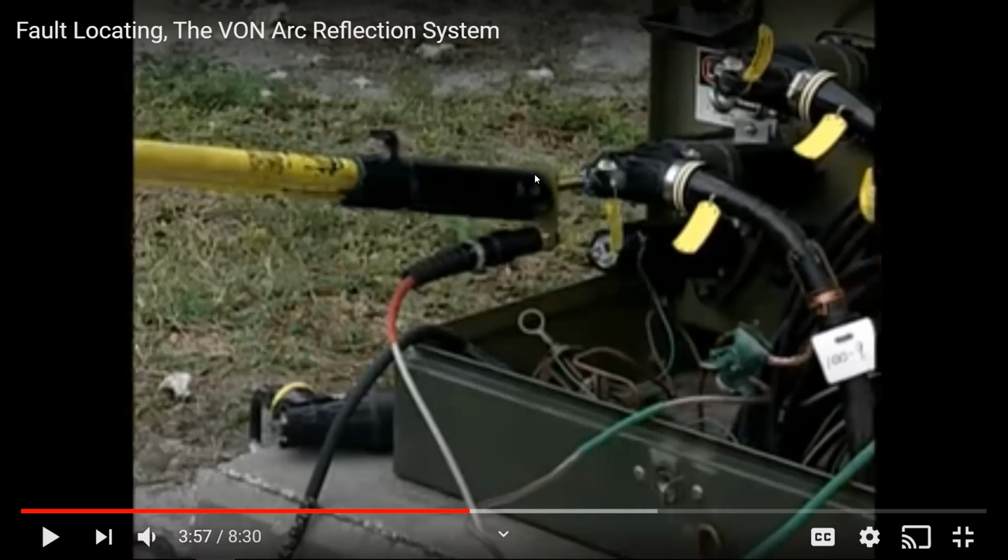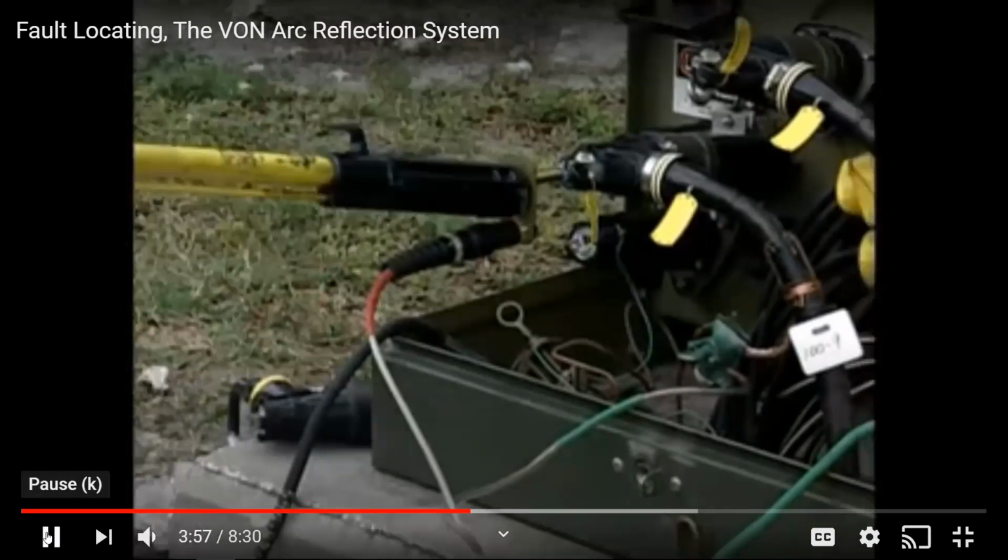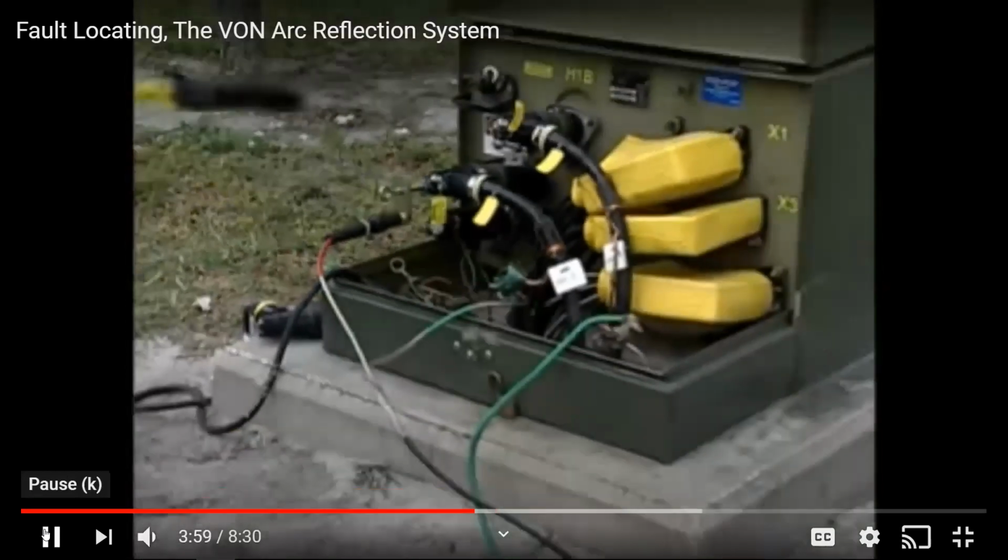He doesn't say much about it, guys, but once he takes this stick off, if you're walking around this area or standing around this area, this is brass, and it is an open live conductor. Now, depending on your machine, this can get up to 34,500 volts. So this is an area to stay clear of while you're testing. We're now ready to find the fault.